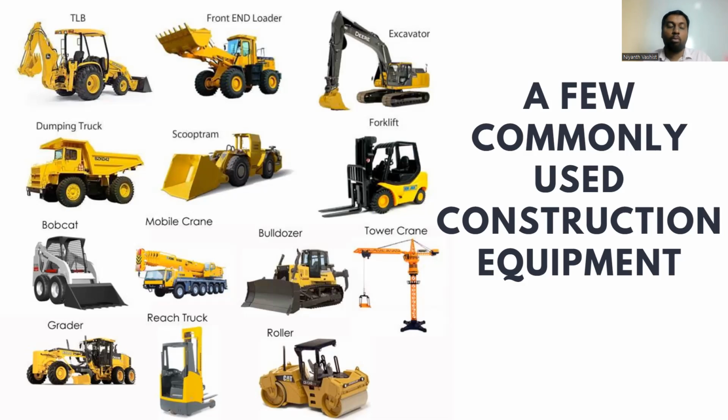The next one will be mobile crane. Mobile crane will be something that you will require on site if you need it in 3 to 4 places. Mobile crane you'll not be using for very high skyscrapers. It will be used only for up to 8 to 9 floors. But if you want to move around the building, depending on the job site layout. In the previous videos, we saw about the job site layout where the crane will be. That is something that needs to be decided. The next thing will be a bulldozer.